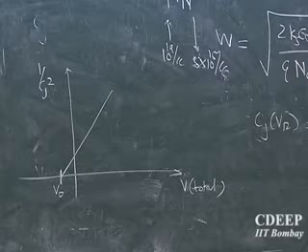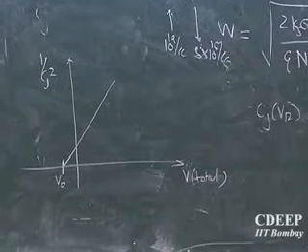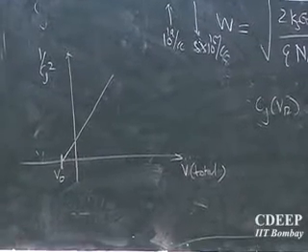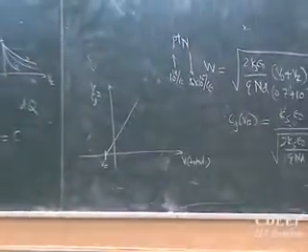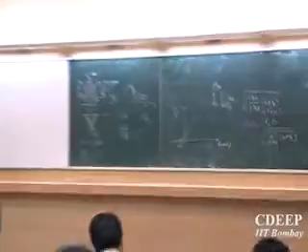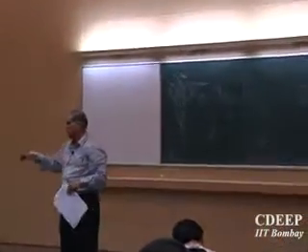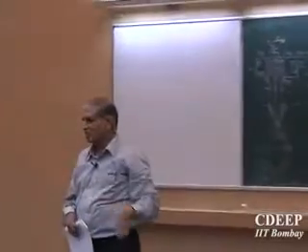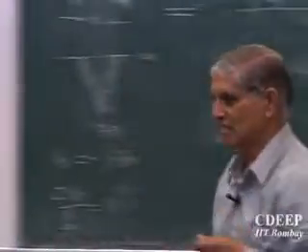So when I check a diode, I measure its capacitance, and it's a step junction. I will get measurement C versus V. Plot 1 upon C square versus VR. As soon as I draw the line, the intercept on the x-axis will give me the value of built-in voltage. And as I said, the value is given by NA and ND by ni square. NA is always assumed to be very high. So ND is known, whatever ND you would have been using for this device.